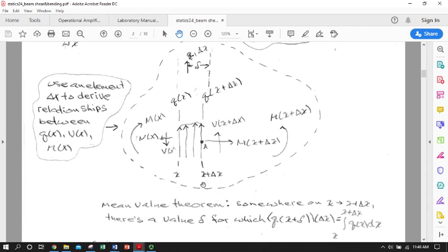It's kind of a little square here, I'm moving my cursor to define it, a little bit of beam. The delta x direction goes between this point at x and this point at x plus delta x, so the distance between them is delta x wide. We don't have to worry about how thick the beam is or how deep it goes because we're considering it to be slender. So we don't have to worry about rigidity and moment of inertia of the cross section, all those things you would worry about if you were going to actually design the beam. We're just going to load it, so we only need to worry about the x direction. Okay, so we have a differential element.